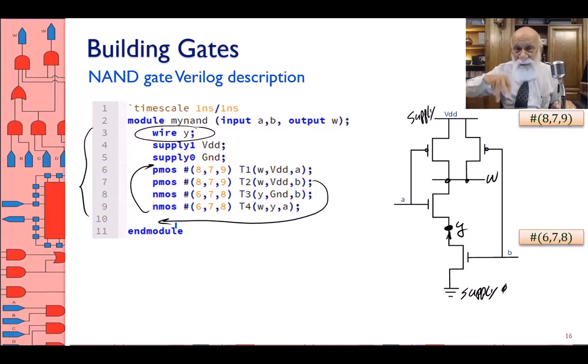For as long as the namings stay the same, this structure defines a NAND. And here the same way. For as long as the connections are defined properly, whether you write the PMOS or the NMOS first, it's not a procedural language. It's not C programming.